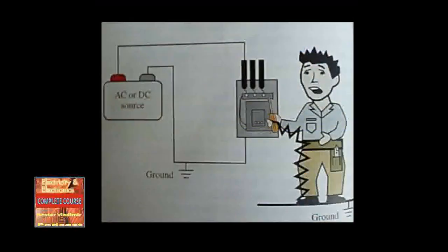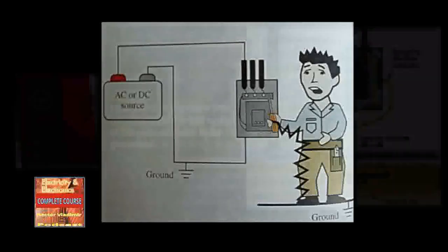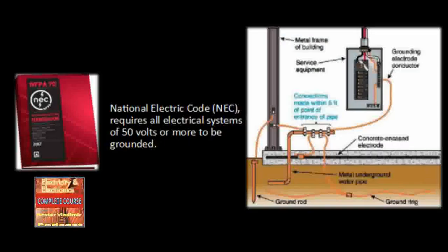If a person touches an energized conductor, that person can easily serve as the path to ground. As shown in figure 2-21, an electric shock is experienced. Also, if a system experiences an electrical fault, the metal enclosure or conduit may have a higher voltage potential than the earth ground. Thus, a person touching the enclosure or conductor can experience electric shock.